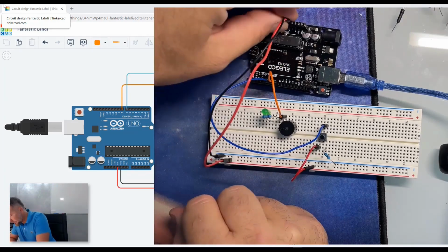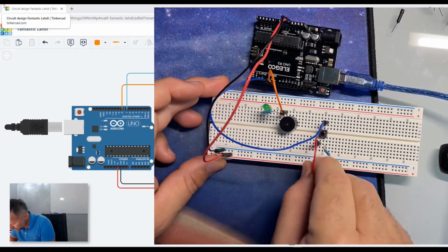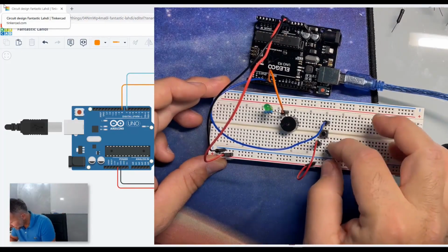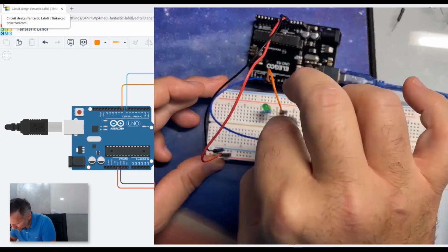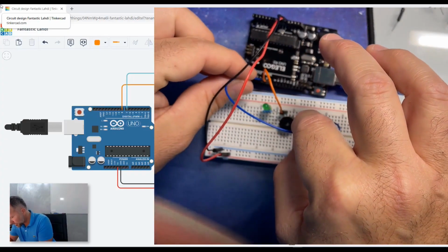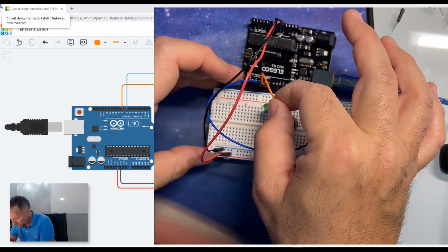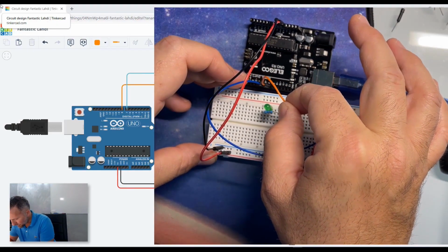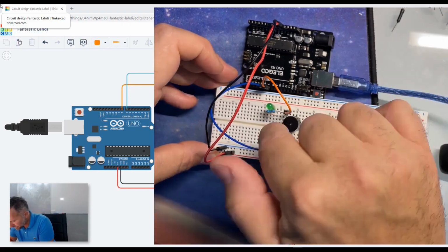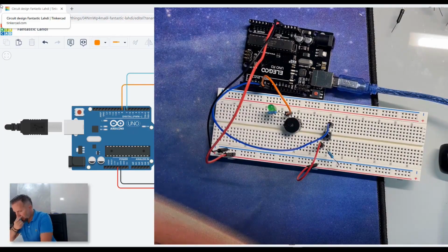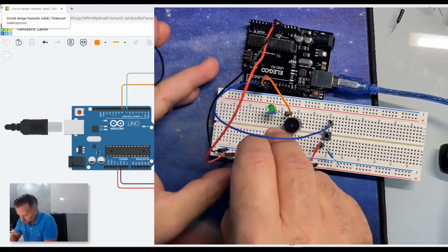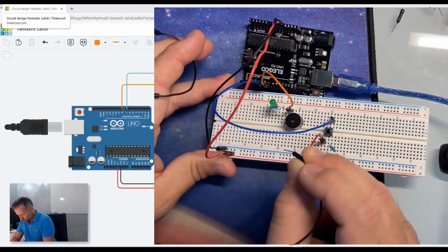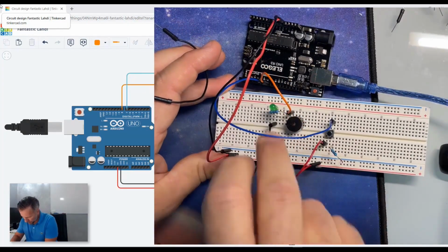The connections, ground and power, are brought to the breadboard, the 5 volts set as a reference on the button on the side. At the bottom, when I press the button, this voltage transfers to pin number 7. We read the state of pin number 7 when it is high. We power this wire that I used, in this case orange, which will go to power both the buzzer and the LED. I forgot the 2 grounds, both of the LED. So the cathode of the LED obviously goes to ground.